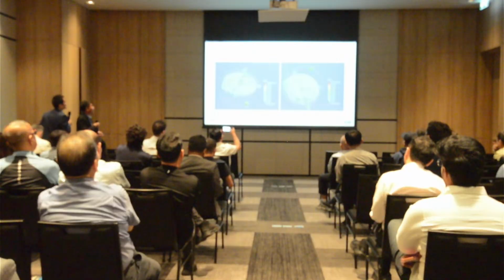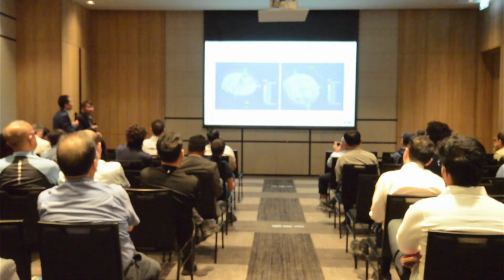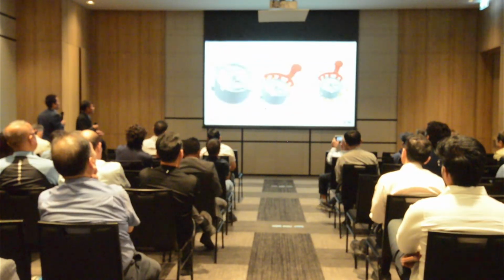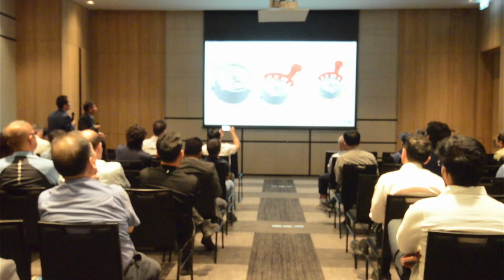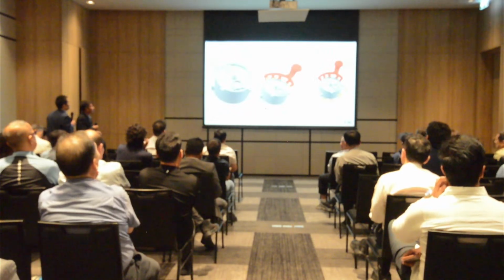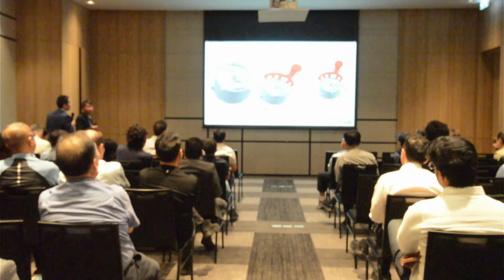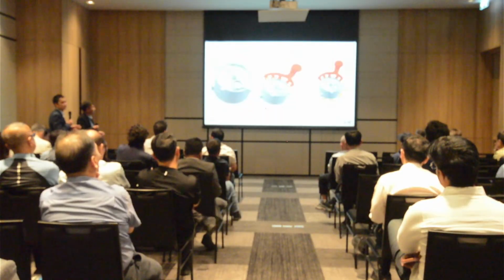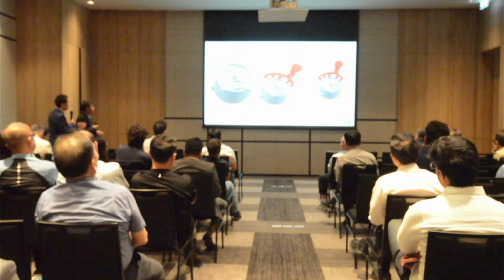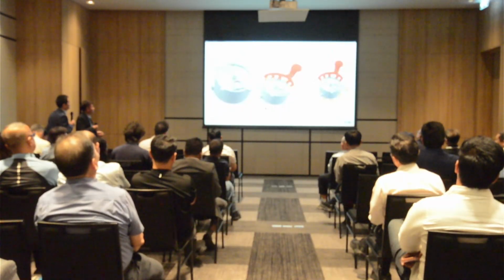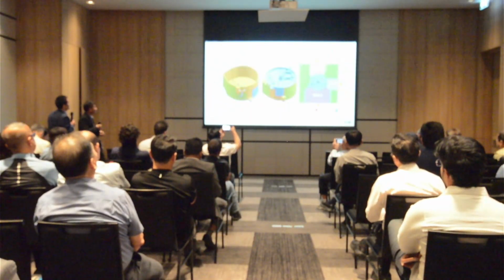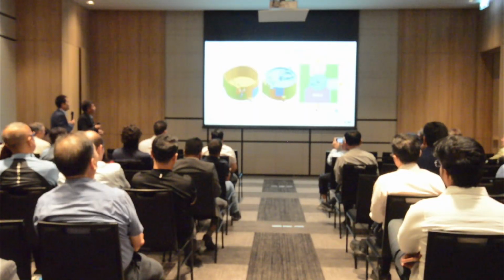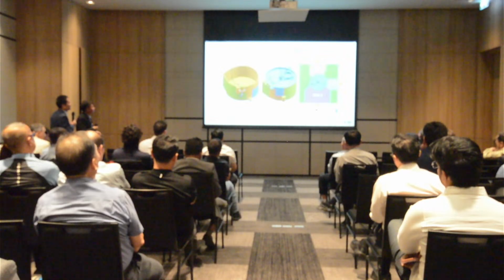This is the hotspot analysis from the mold flow. You can see many hotspots, which carry the risk of shrinkage porosity. This is the gating design: the gating, runner and overflow. You can see the gating direction follows the hotspot analysis to reduce porosity and give better feeding. Then we design the moving side, fixed side, and parting line, including the slides.